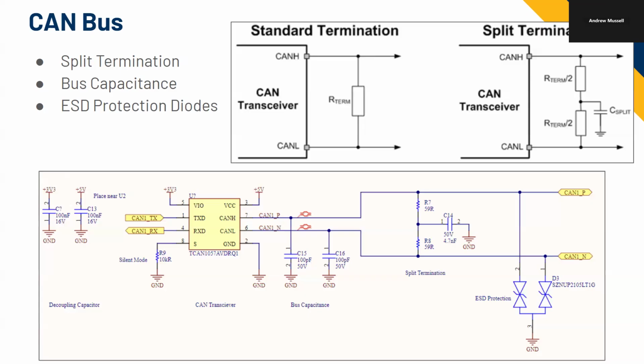Why wouldn't we just switch the ESD connection out with a fuse? Doesn't the fuse just trip every time it gets shorted or touches high voltage? Fuses are current protection, so they'll burn if there's too much current going through them. But physical fuses are a little bit wonky, because the way you design real fuses is that when they conduct a certain amount of current, they heat up a really small conductor, and then that conductor burns. So it's actually temperature dependent. If you operated your fuse and had something to cool it down, it wouldn't burn.